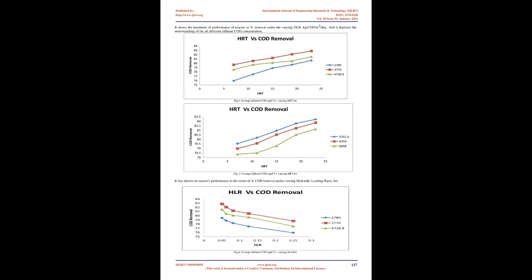Experimental methodology. For the startup, the bottom of the reactor was filled with the anaerobic sludge taken from the wastewater treatment facilities of Annamalai University, and then fed continuously with the screened domestic wastewater and allowed to stand for 15 days. Throughout the study, the reactor was operated at a room temperature of 30 plus or minus 2 degrees C. After stabilization, synthetic wastewater was used for an experimental study to standardize the experiment.